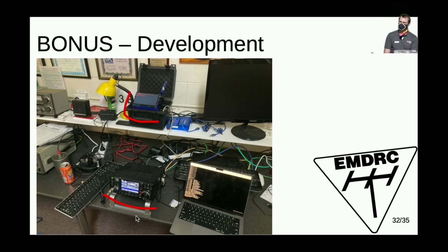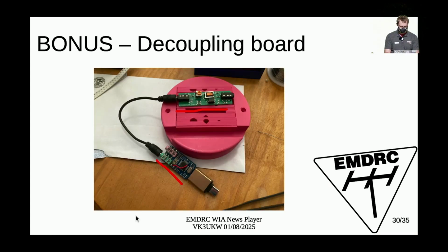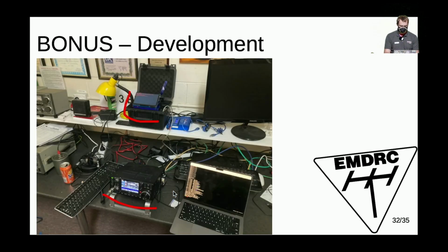That's why I also needed the ICOM CI-V, because the 9700 is controlled with the CI-V, and in that case not with my PTT hack here. We just did the USB connection there, and I've got that in my player. It supports it. You can select what PTT method you want. If you want another PTT method, you can implement it yourself.